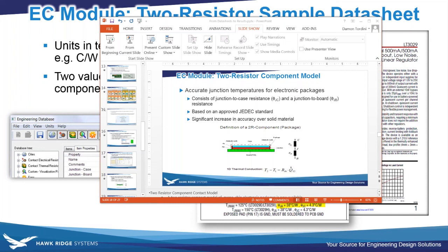These 2 properties generally are going to be the same for a chip, that they'll never change. Sometimes they're described differently. Theta JA, for example, is the thermal resistance to ambient. So if the chip, for example, doesn't mount directly to a board, they might describe it differently. Maybe because it's got some kind of standoff leads. Either way, you can still use the Two-Resistor model for that.